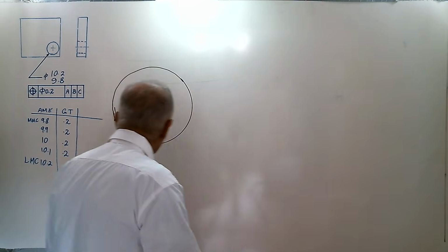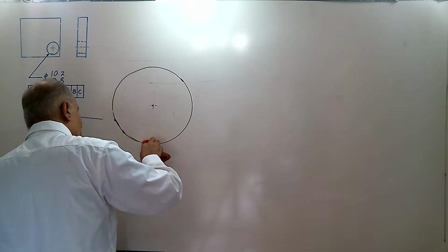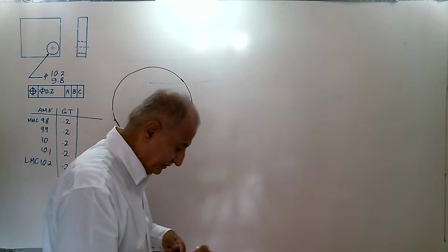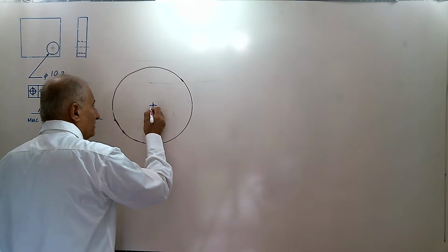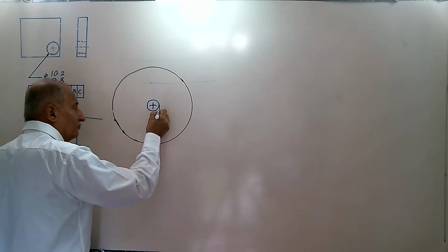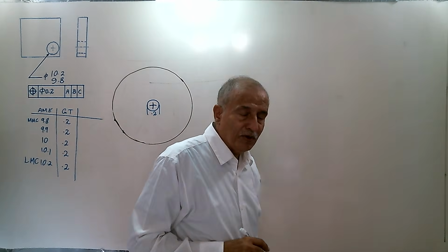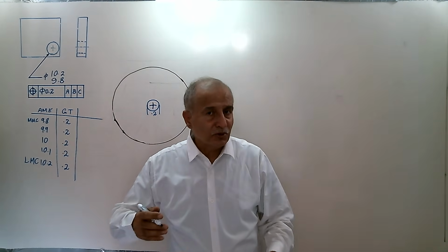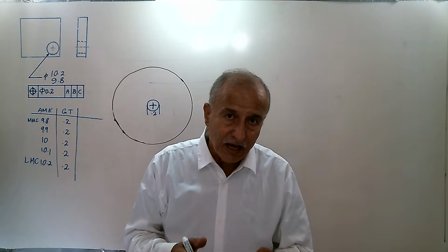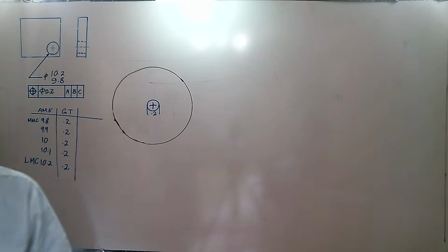This is the hole. Ideal case that is not possible to produce. The hole without error, position error. Then the designer gives the manufacturer a zone which is equal to 0.2 for the error. It means that I know that producing at the true position is impossible. I know that. I gave you actually a space for this error.